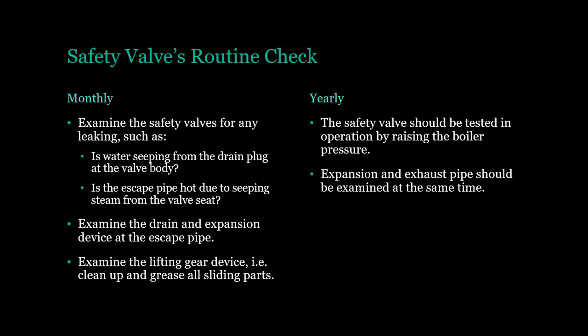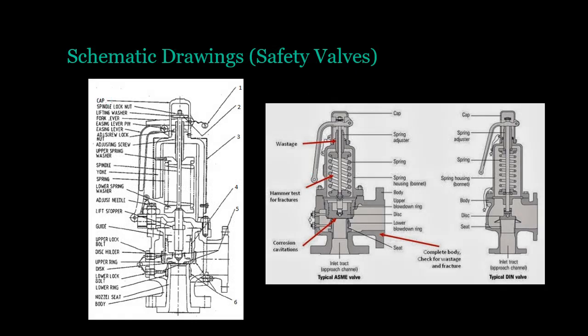Yearly, the safety valve should be tested in operation by raising the boiler pressure. Expansion and exhaust pipe should be examined at the same time. Schematic drawings, safety valves.